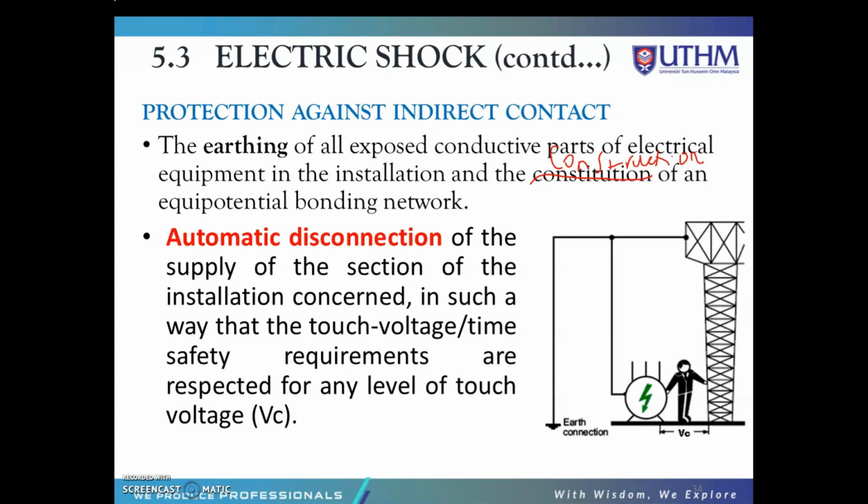Okay, and then we also can use the automatic disconnection of the supply of the section of the installation concerned in such a way that the touch voltage or the time safety requirements are respected for any level of touch voltage VC. In this diagram, VC is here. Touch voltage is the voltage between the energized object and the feet of the person in contact with the object.